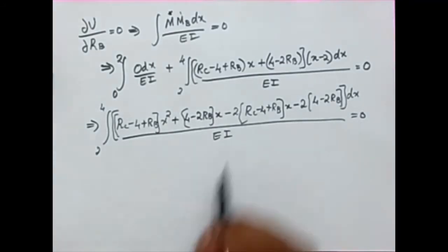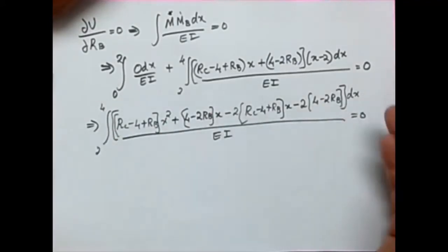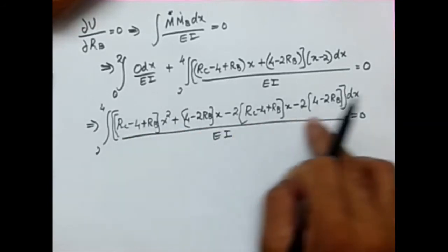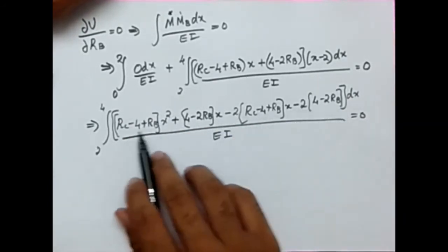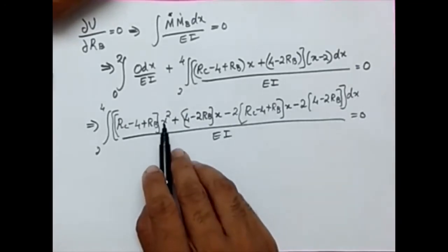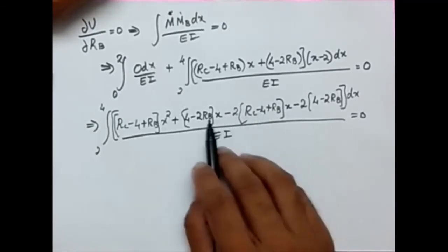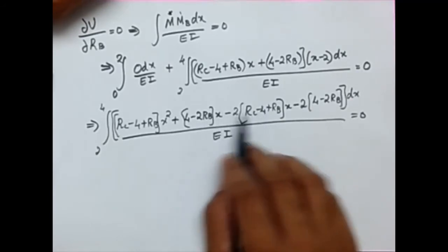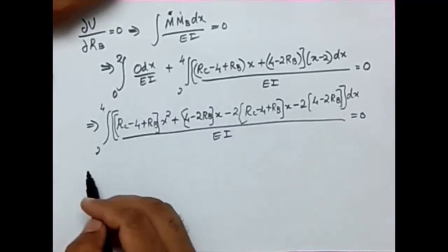Okay. Now ei is a constant. If I take this ei outside and transfer it to the right hand side, ei vanishes because the right hand side is 0. So now I just need to think about this. So what happens when I integrate this expression with dx? There is x square which will become x cubed by 3. These two terms have the magnitude as x, so we can reduce this before substituting the limits. So I am writing it again.